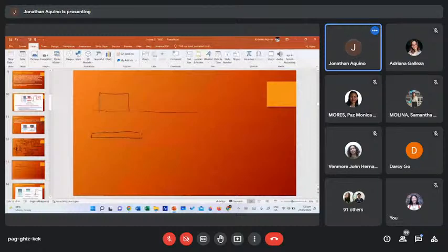367.76. Okay. So what else do we need to get the moment of inertia? Nothing, right? Okay. So the moment of inertia about the neutral axis is simply bh cubed over 3. The moment of inertia of the rectangular section at the base is bh cubed over 3, where b is 300 millimeters. So bh cubed over 3 plus...